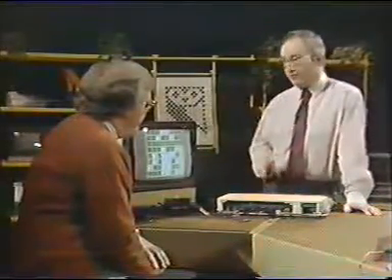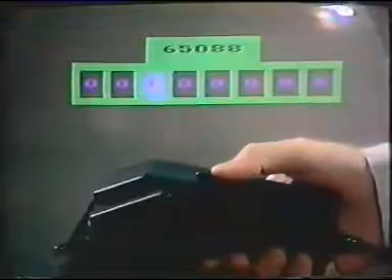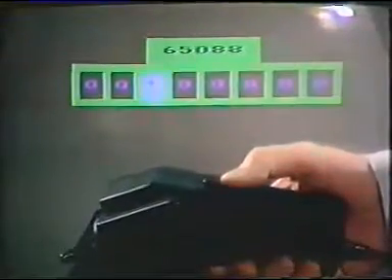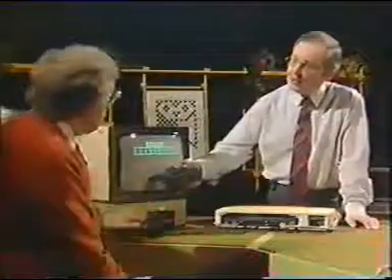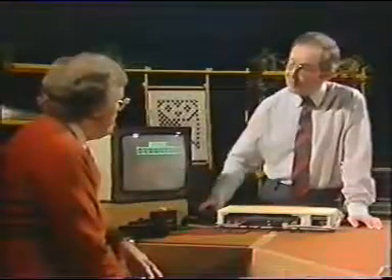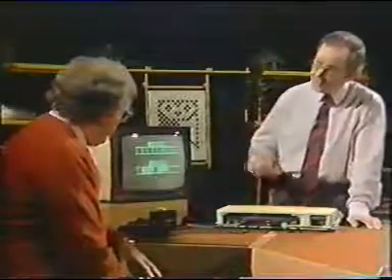Well, what happens inside the computer? Well, we've got a couple of those addresses set aside, not for RAM, random access memory, but in fact for input and output devices. And here's one particular address, 65,088, which in fact is an input connection. And when I push this button here, the bit changes, and if you push the button on your games paddle, a different bit changes. So the input from this is being fed into this address, and we can sense it there. And the output is at another address.